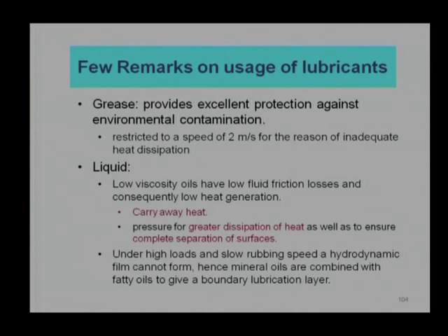Coming to the liquid side, you say that we prefer low viscosity oils. The major reason is that there will be lesser shearing. If it is a Newtonian fluid, we can say shear stress is proportional to the viscosity. Lesser the viscosity, lesser will be the shear resistance. Lesser the shear resistance, lesser will be the friction force. Lesser the friction force, lesser will be the heat generation. So, low viscosity oils should be preferred compared to high viscosity oils, provided minimum film thickness is maintained.